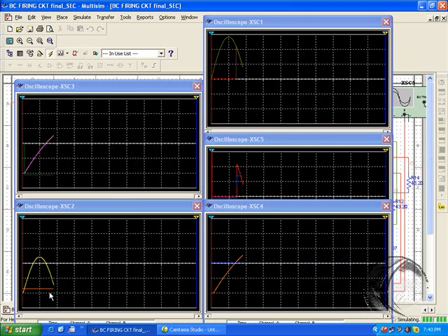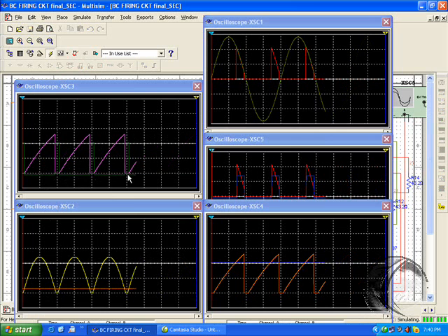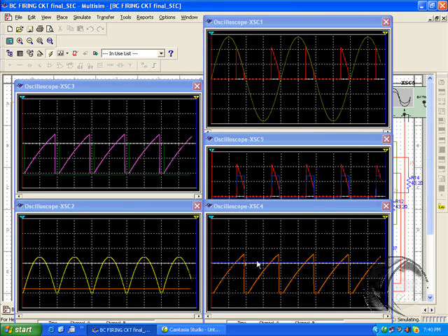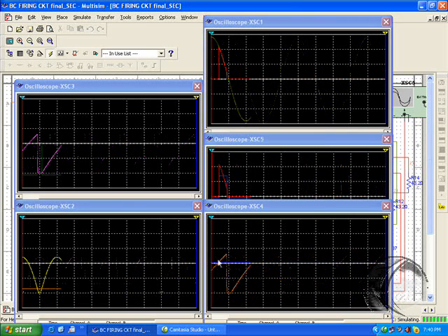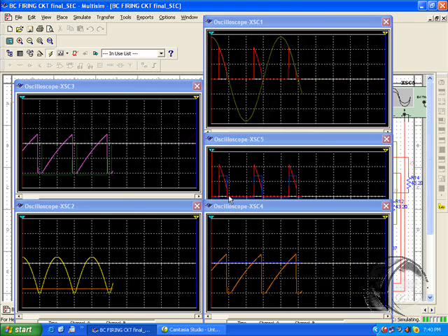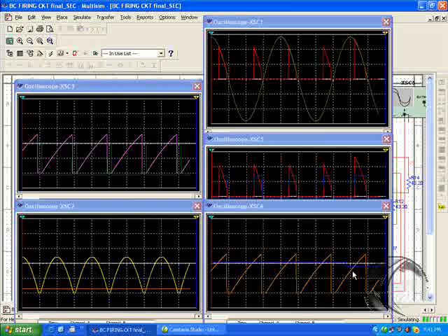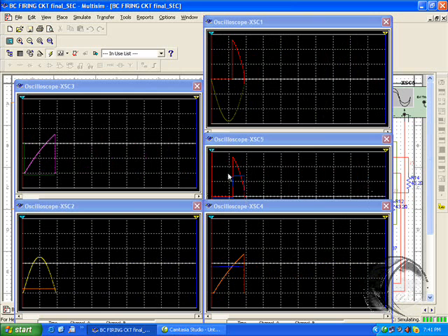Now see, this is the pulsating DC, this is the fixed DC, so we get this kind of pulses, and then based on which the sawtooth voltage is generated, and this sawtooth voltage is compared against this voltage. Now if I change this, the on time width is this, and this is the delayed angle. Now if we change the fixed voltage here, you see this width is increasing, this width has increased. Now if I further see, the width will be increased further here,